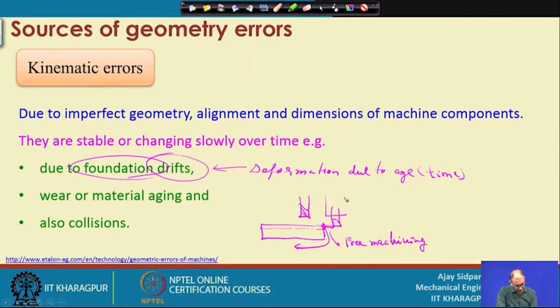You have a spindle system here. This particular force will be in this direction, so your spindle will try to move in this direction. After the whole thing has moved here, now you want to cut an under depth here. Now your location of the cutting tool is here. Again you have free machining here, or air cutting, so no force, and then you suddenly strike this location with your spindle system here.